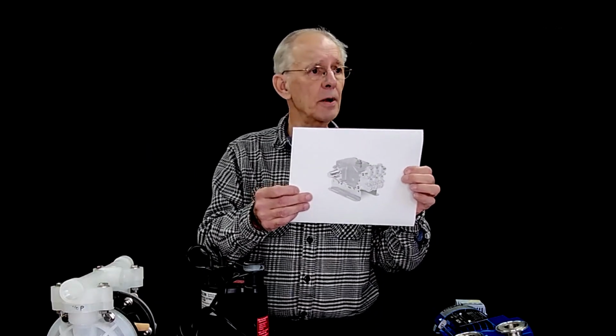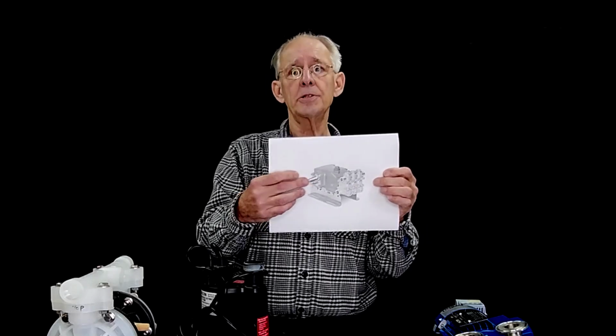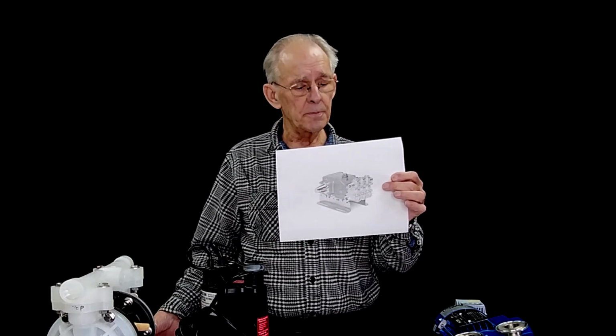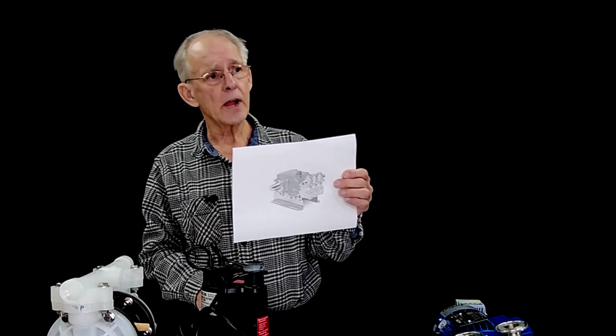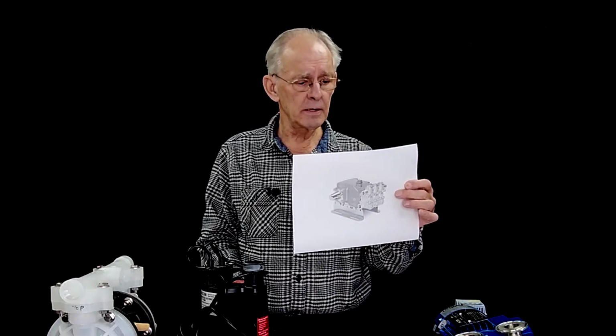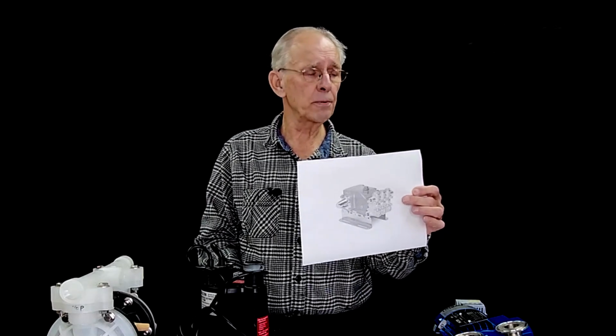It's another positive displacement pump. This is a pretty typical pump used on high pressure washers. And this is a piston pump. Piston pumps are used for very high pressures, low flow but high pressure. And these can produce pressures high enough to be used in a water jet cutting machine, where they use pressures over 60,000 psi. The downside to piston pumps is they can't tolerate any abrasives.